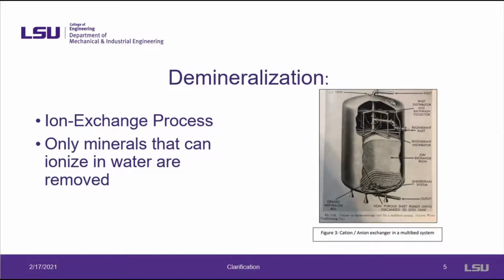Reverse osmosis often occurs after the cation and anion exchangers to allow for additional filtration. This process forces water through a membrane that will trap minerals and allow only filtered water to pass through. The membrane filter should be backflushed periodically in order to avoid the excess buildup of minerals on the filter.